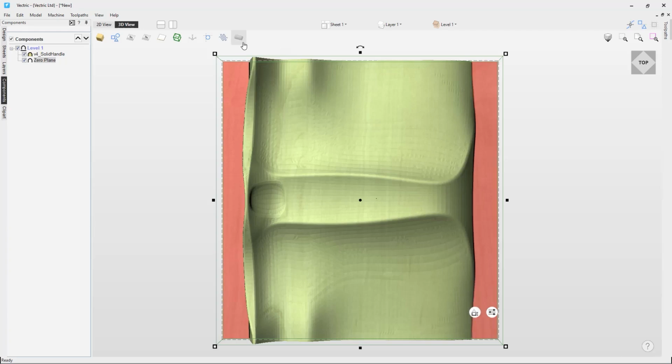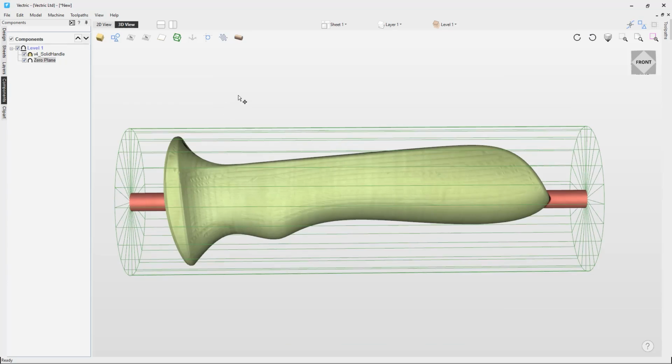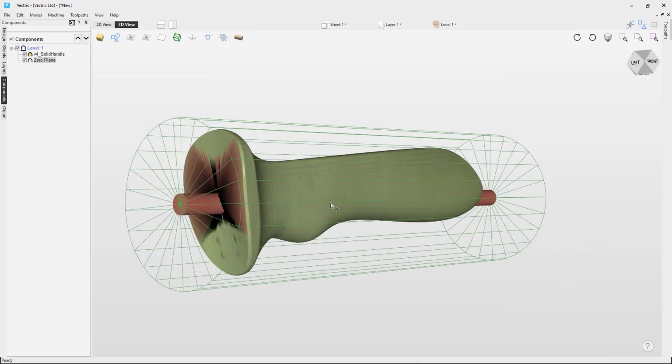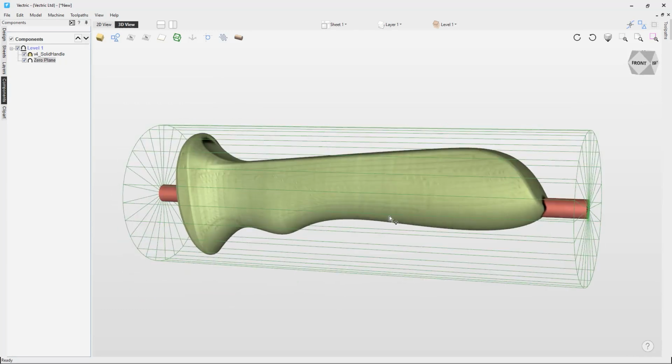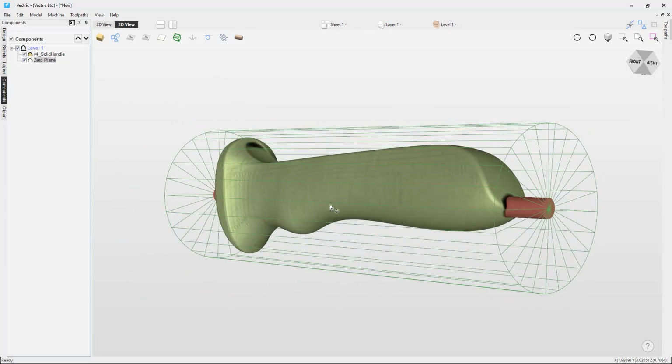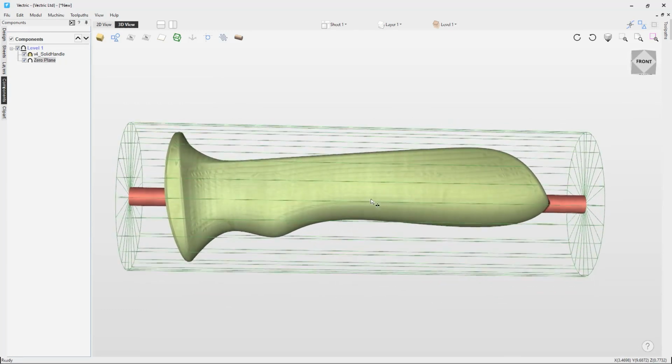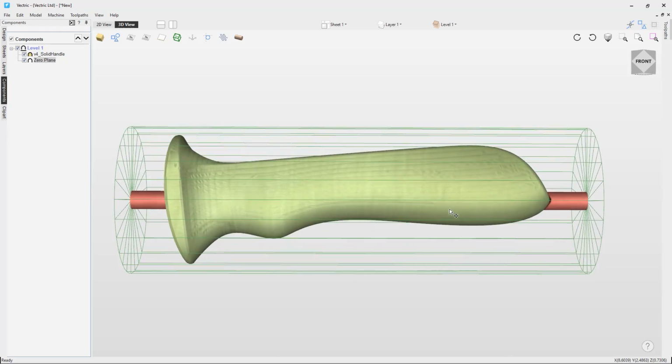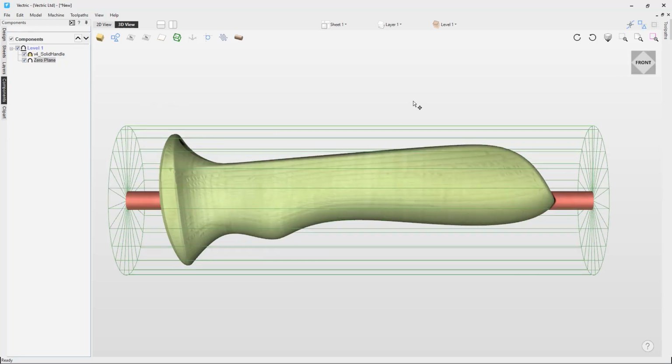And then what will happen is when we go back to wrapping this, you'll see I now have some tabs. So it's increased the base height of that zero plane to help us naturally create a tab there. And there we go. That looks wonderful. So when it comes to actually machining this now, we can cut these away after we've machined away the rest of the material, and this will still be on the machine, so we can safely cut it at this end, cut it at that end, remove it, and then sand down what we need to get it looking like we want to. But with that in mind, we can now have a look at actually creating some toolpaths.